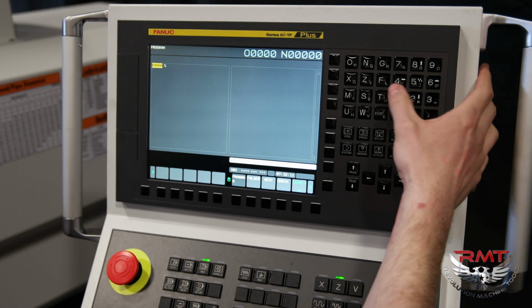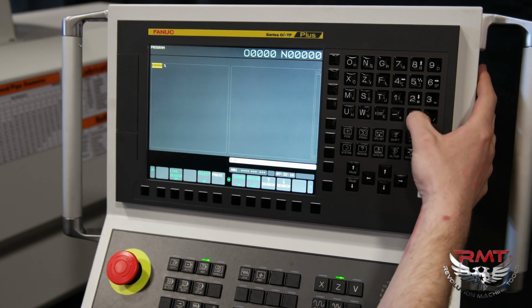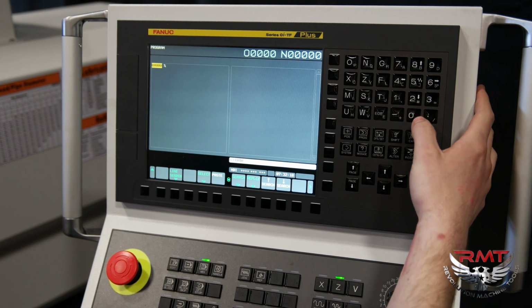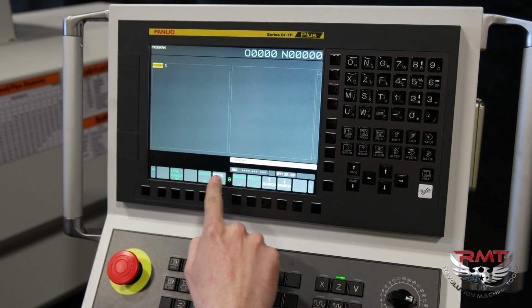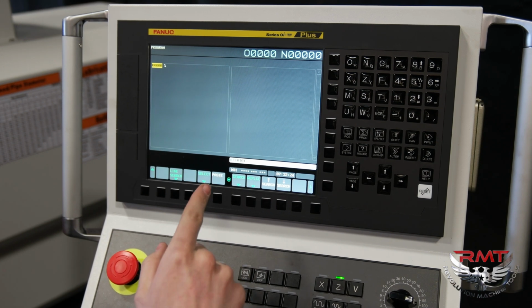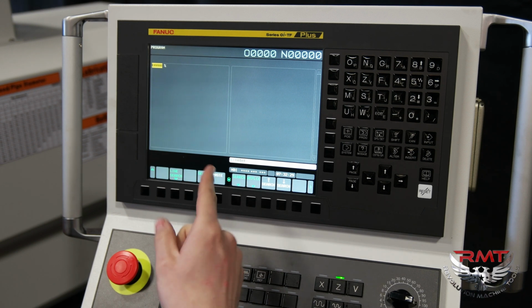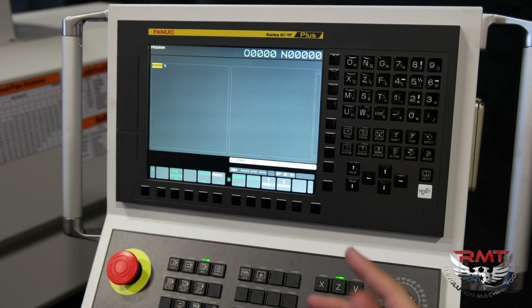I will then type out tool and then whatever number I'm using. So in this case, I would suggest using tool 1, and it is typed out as tool 0101. This is the same format for any other tool, but replacing the 1 with the appropriate number.